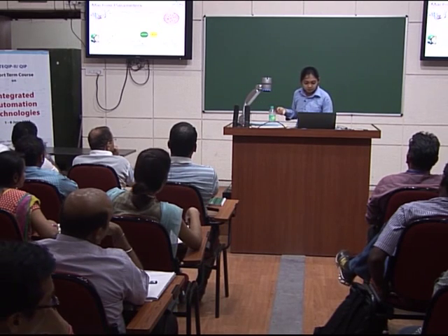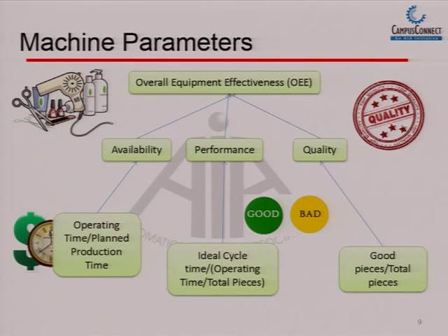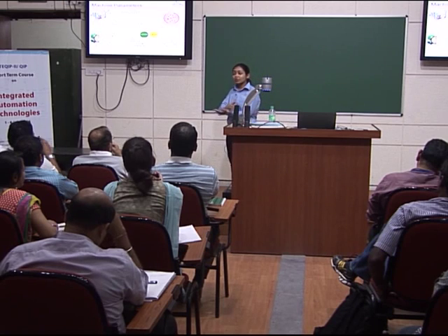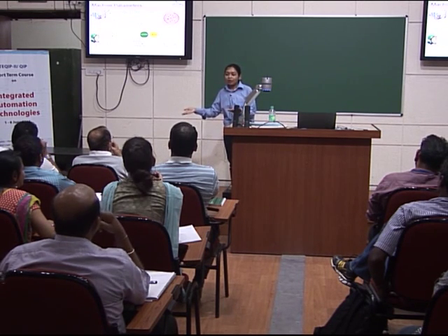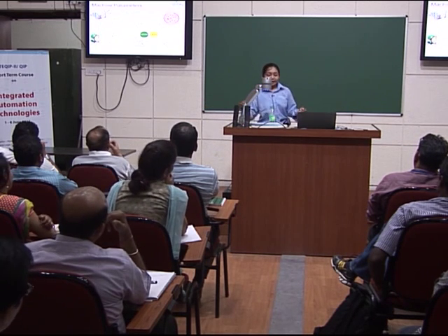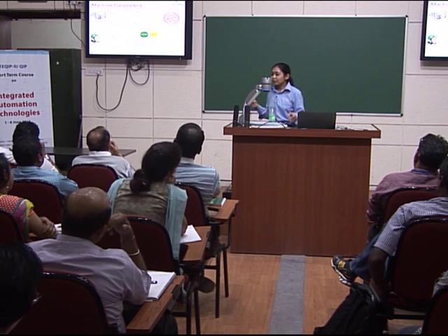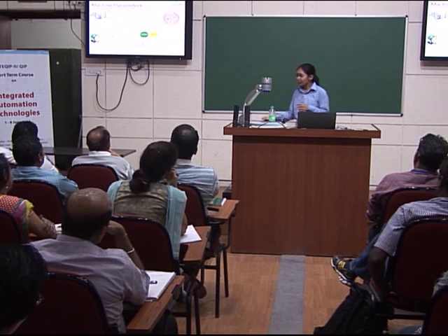But will it not be standardized? Pardon me, sir? If somebody measures it over 1 day, somebody measures over 1 month, these two are not comparable figures. Yeah, you don't consider 1 day's OEE against 1 month's OEE. We consider Tuesday's OEE against Friday's OEE, or July's OEE against August's OEE. It's not like I am seeing OEE of July, so tomorrow I'll see the OEE of September, how is it going, so where is the fault in the machine?